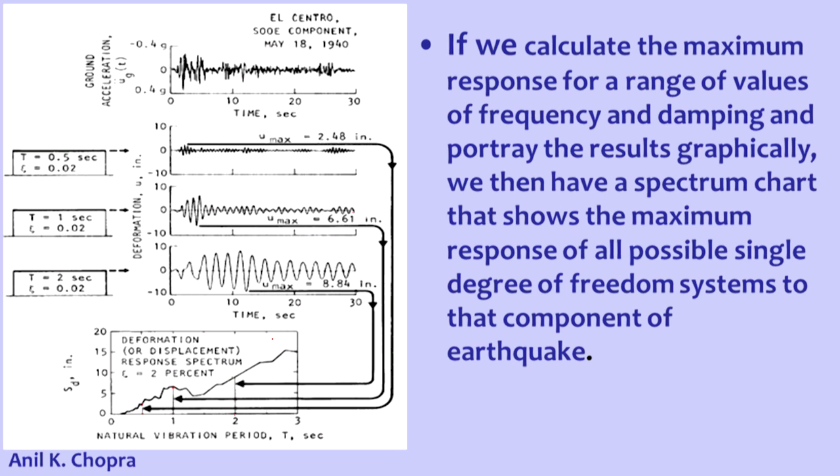So this is the concept of response spectrum. This is how we construct a response spectrum. You can see here, if we calculate the maximum response for a range of values of frequency and damping and portray the results graphically, we then have a spectrum chart that shows the maximum response of all possible single degree of freedom systems to that component of earthquake.